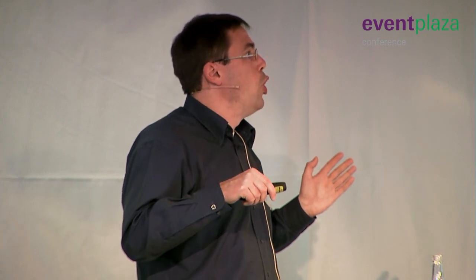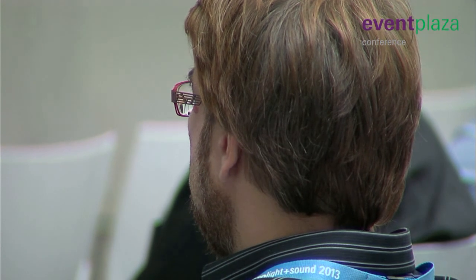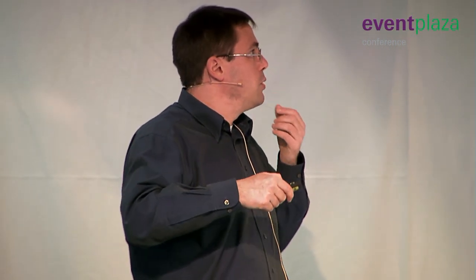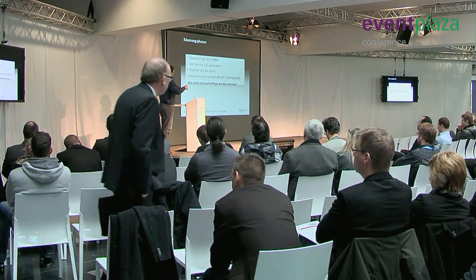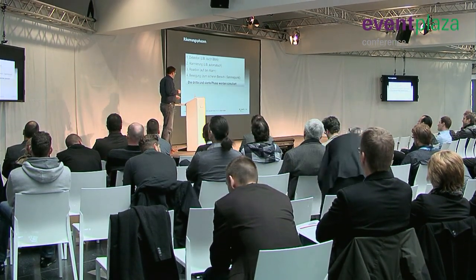So what kind of evacuation or emptying phases do we know? I actually mentioned the 4 phases, and again, it links back to what I've presented in general. You simulate the 3rd and the 4th phase, that is really the reaction and the movement. The situation of detecting a fire, making an announcement and ringing the alarm is not being simulated. But when you talk about the time it takes to evacuate and move people, you need to add the time needed for the fire detectors to detect the fire and to announce that risk to visitors.